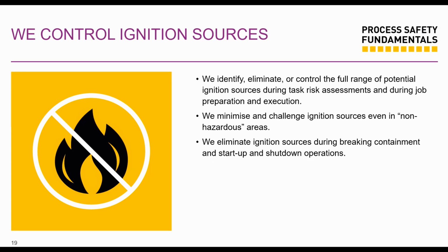A couple of examples also. I said I was going to give an example for each one. You want to weld a bracket on a pipeline or on a pipe rack, to keep it in place. And the fire watch says, hey, let's have one final gas check. Or maybe we're supposed to have continuous gas monitoring, and it detects hydrocarbon vapors when you want to do that welding.